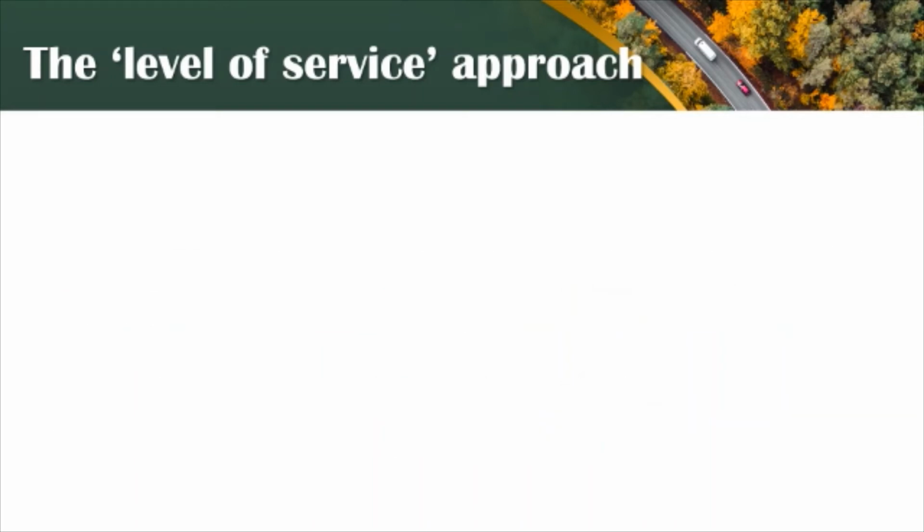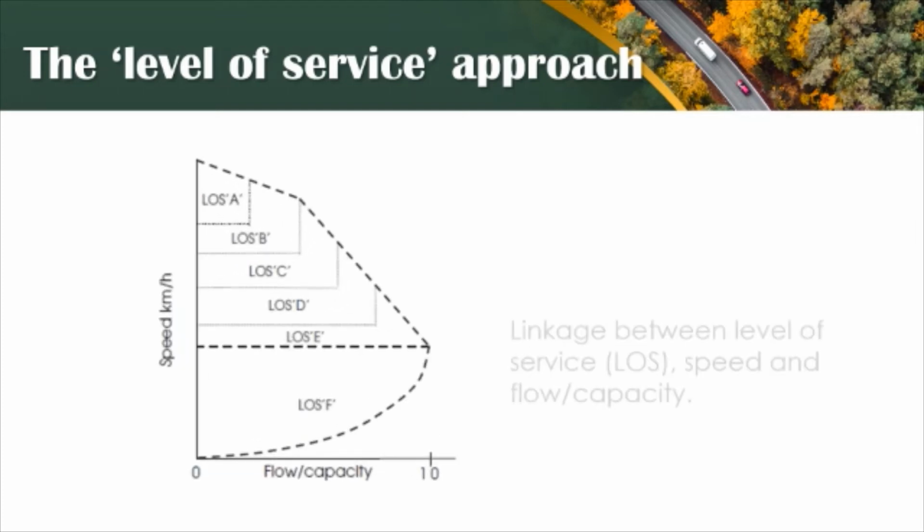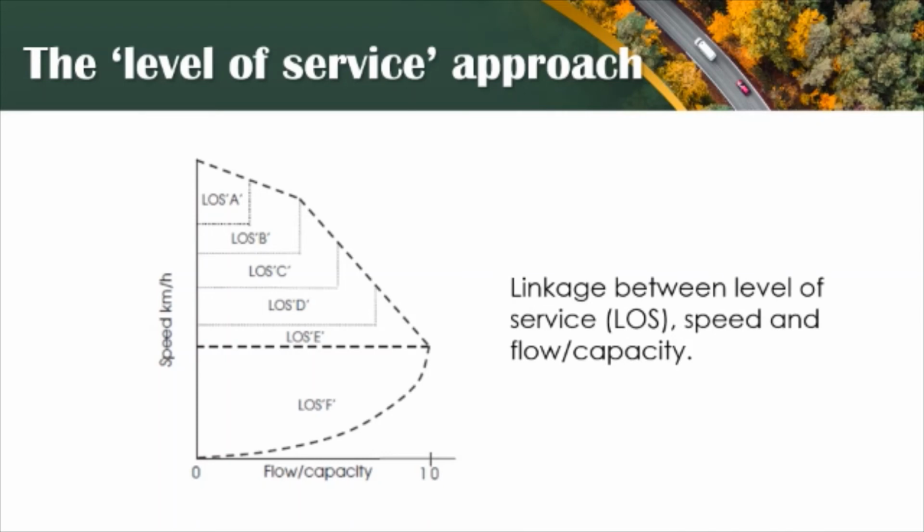These conditions and their associated relative speeds and flows are illustrated in this figure. At the level of Service A, speed is near its maximum value, restricted only by the geometry of the road, and flows are low relative to the capacity of the highway given the small number of vehicles present. At the level of Service D, flows are maximized, with speed at approximately 50% of its maximum value. Level of Service F denotes the breakdown condition at which both speeds and flow levels tend towards zero.